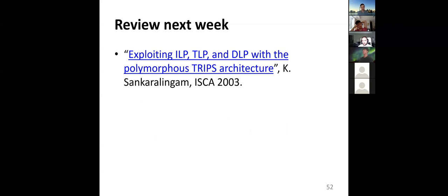Yeah, next week you're going to review the paper from Karu on exploiting ILP, TLP, and data level parallelism, all these different forms of parallelism, with the polymorphous TRIPS architecture. The TRIPS architecture is a data flow architecture. This is not the usual architecture, so that's why you're reviewing it. Today I'm going to cover more classical architectures, but you're going to read about data flow architecture. This is probably different from everything you've seen before, right? This is where it's not the instructions that are the boss driving the execution. It's where the data is driving the execution. So the data activates the compute, not the other way around.